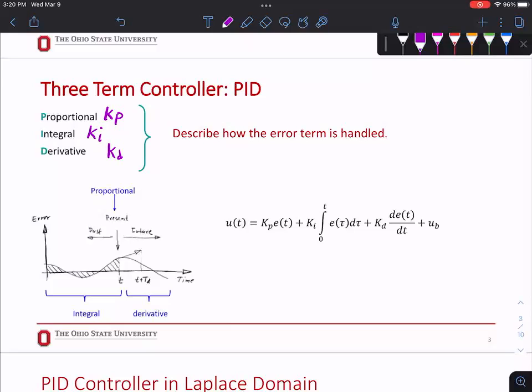If you think of this graph, the derivative is like the tangent at that point of the system. So you can't tell exactly what the next point is, but you can predict. You don't predict 10 hours in the future. You predict the immediate future, what kind of error you're going to get, and you compensate for it. Then you go, okay, I'll compensate for like 90% of it. Then you see it is in the past now, right? So it goes to integral. See how much error you accumulated, and then you're at the present, you fix it with some proportional, and then keep going.